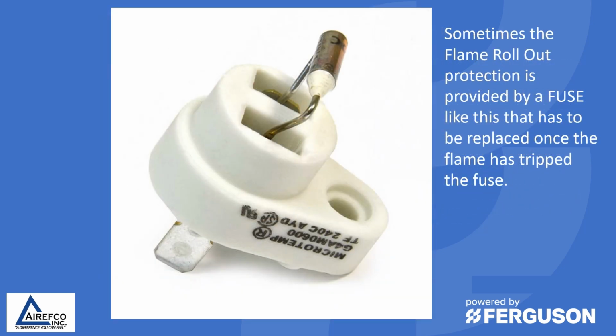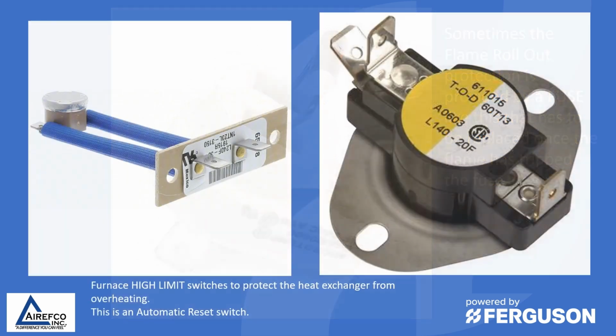Sometimes the flame rollout protection is provided by a fuse like this that has to be replaced once the flame has tripped the fuse. Some more examples of safety switches are furnace high limit switches that are designed to protect the heat exchanger from overheating. These switches are automatic reset.